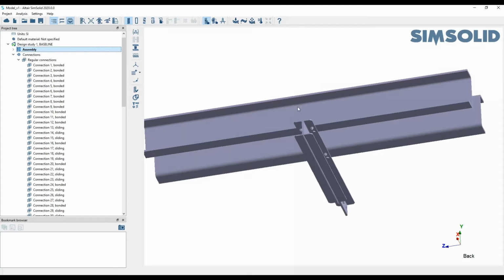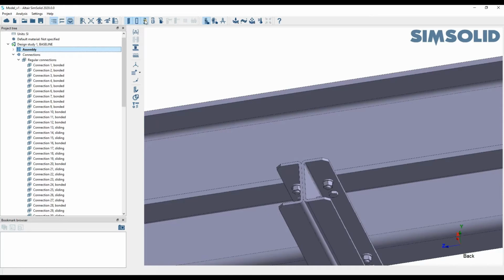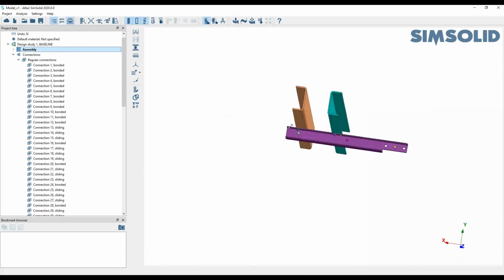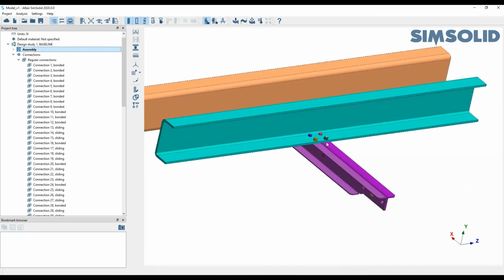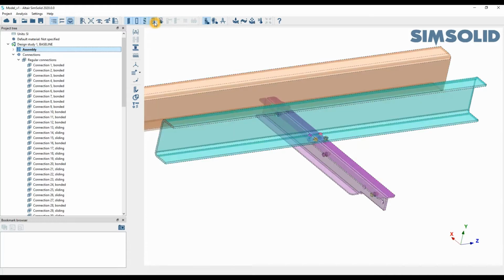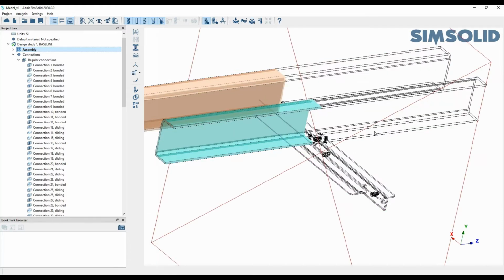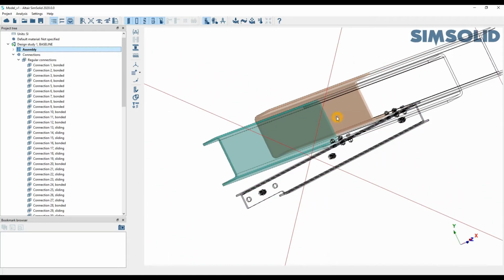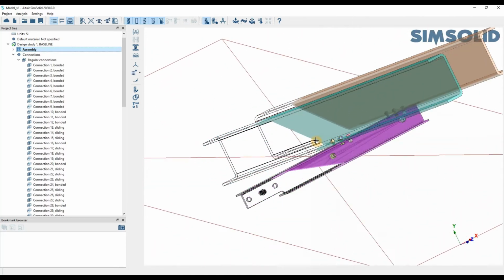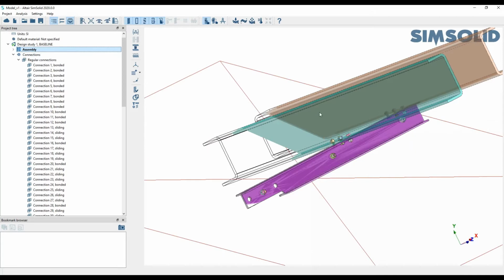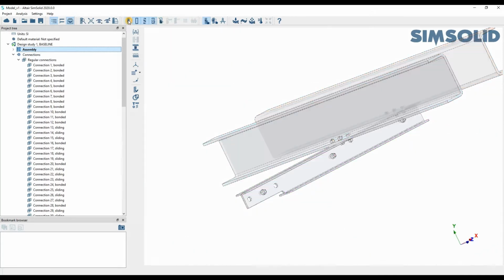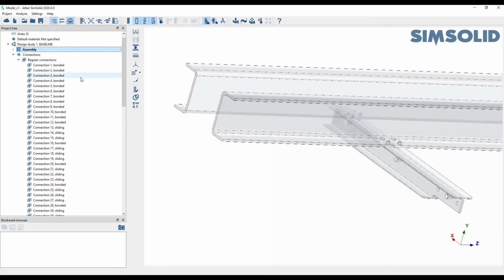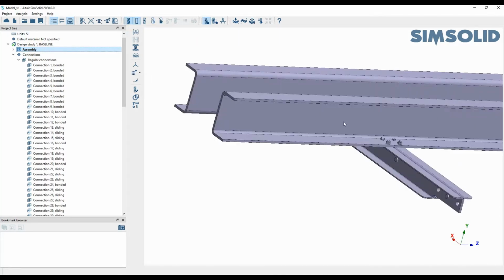Along the rest of this bar here, you have all of the different visualization tools that you need to see your different parts. You can make it wireframe, so you're looking at the edges. You can specify all your parts in different colors, so you know exactly where they are. You can make them transparent, and you can also implement a cut cross section through it. So you can see through it all, and you can rotate it around to reach other areas.